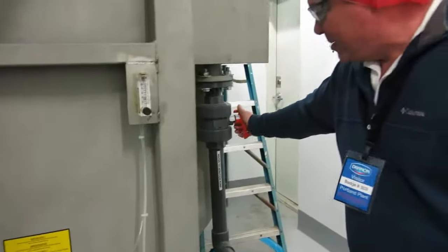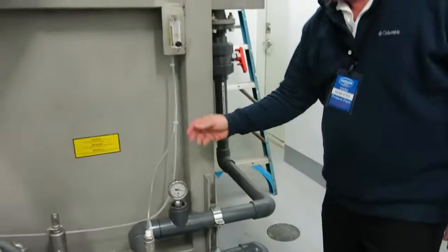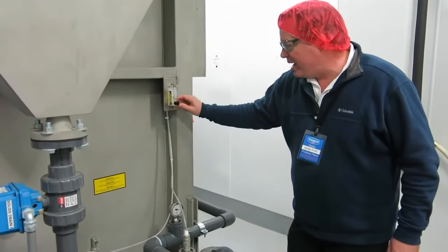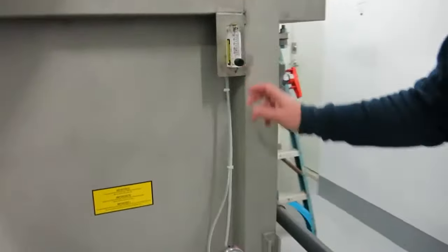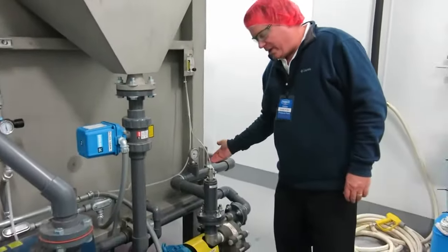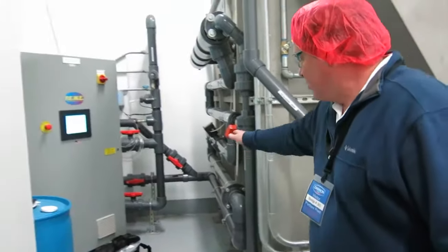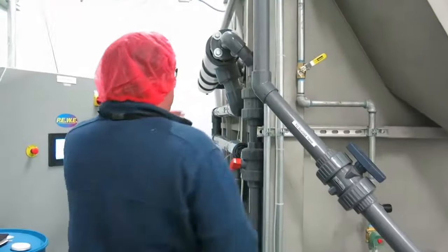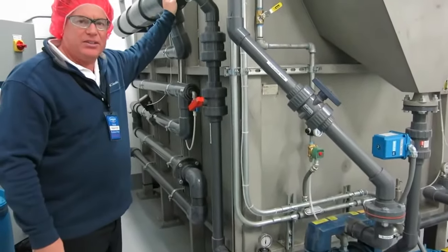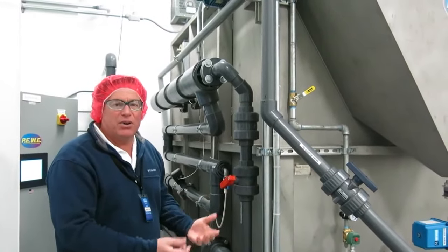And we do that by setting our feed valve coming from the clear well into the head of the pump. And we can adjust the amount of air going into the system through the rotometer. Right now we have 43 cubic feet an hour going into the system. So between controlling the air and water going into the pump, and maintaining the discharge pressure through this throttle valve, we can then inject aerated water into the system. And every time the system comes on, the DAF will get a 20 to 30 micron bubble, creating a great mat for floating our solids.